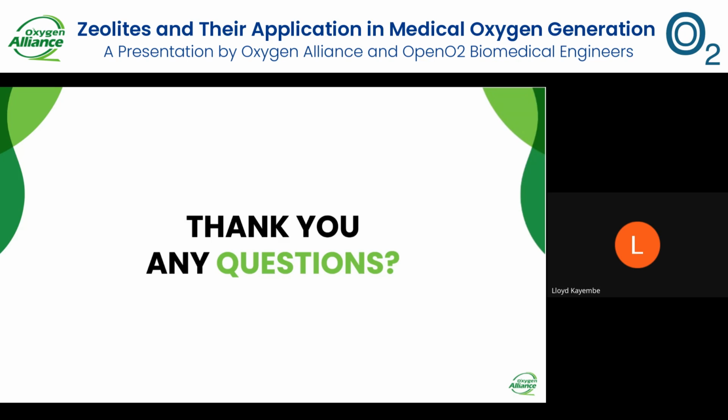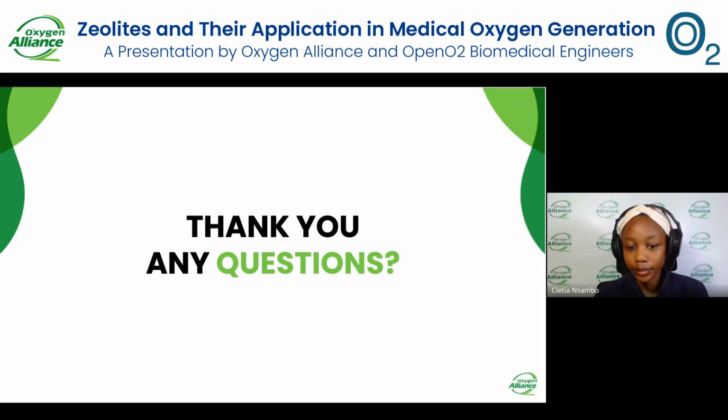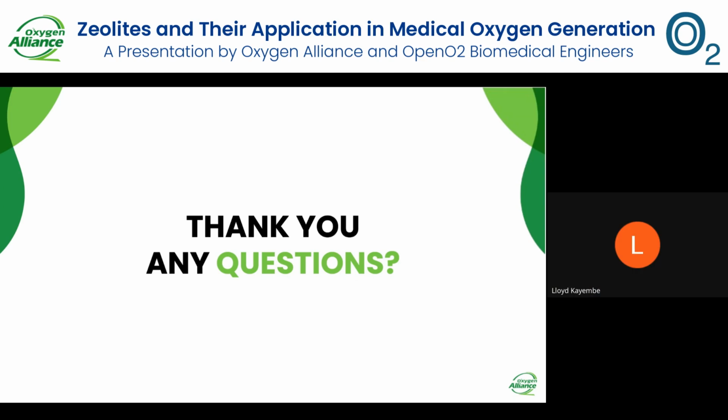Over to you, host. I think they're also asking about the pressure itself, apart from the temperature. Do you have the working pressure for the PSA generator? I will comment on the typical working pressure for portable oxygen concentrators. That's actually 20 to 30 psi. That's the pressure in the sieve bed. I hope that has answered your question.